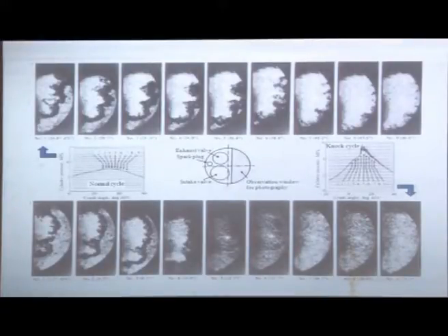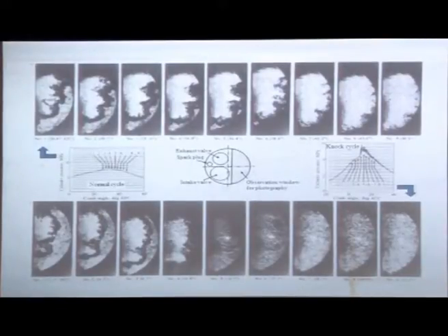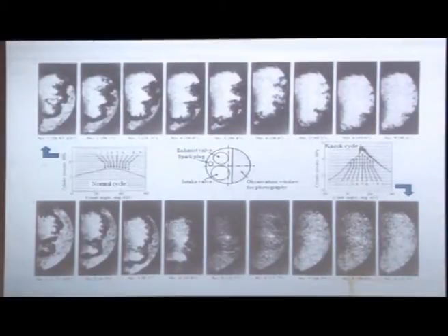And the piston is also hinged at one gudgeon pin, so it will lead to vibrations, and there is no room for the piston to vibrate. So actually the piston goes and hits the walls on both sides. It can even physically get damaged. The rings can actually get embedded into the grooves because of this hitting. So many bad things can happen.